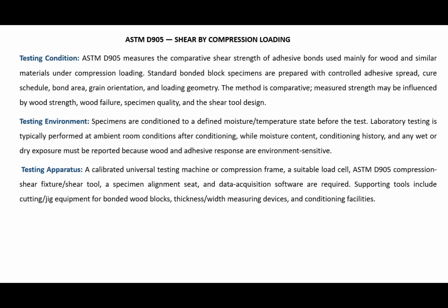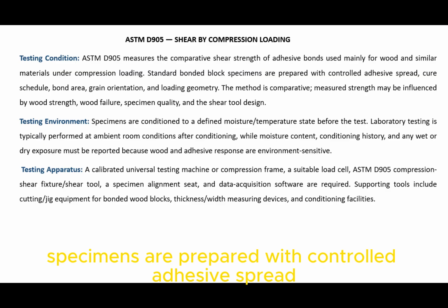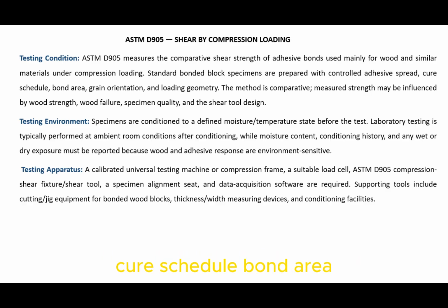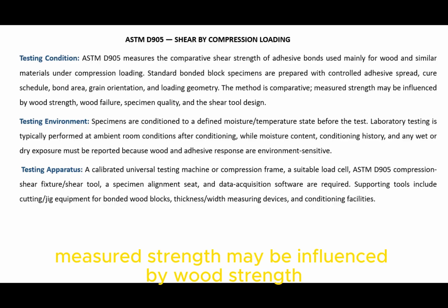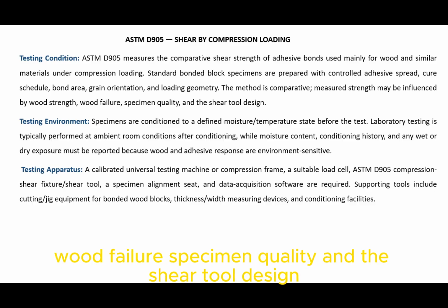compression loading. Standard bonded block specimens are prepared with controlled adhesive spread, cure schedule, bond area, grain orientation, and loading geometry. The method is comparative. Measured strength may be influenced by wood strength, wood failure, specimen quality, and the shear tool design.